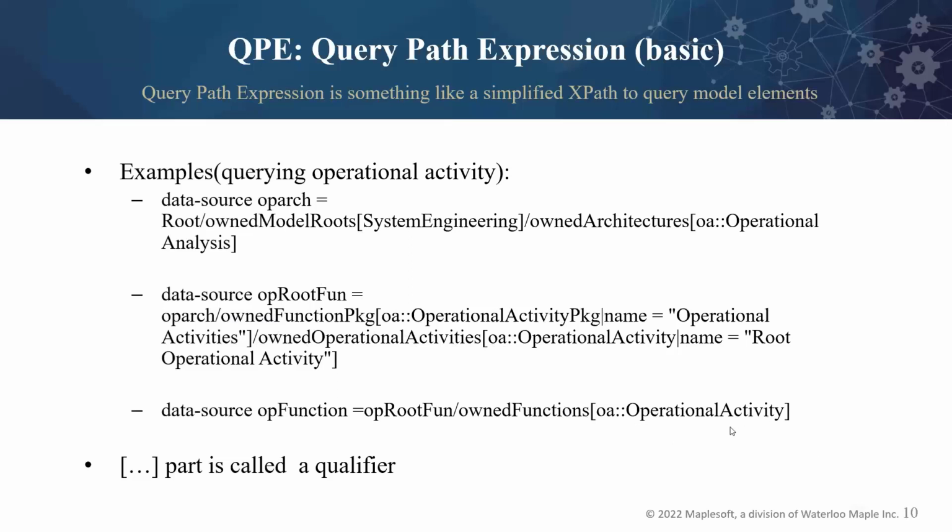This is how we navigate, and again, this navigation is similar to how your Capella model is structured. The main advantage is that once you create a configuration file and these navigations, you can use them across different projects. Given that the Arcadia methodology is the same and the way the project is contained and structured is the same, we can reuse the configuration files for different projects that we want.